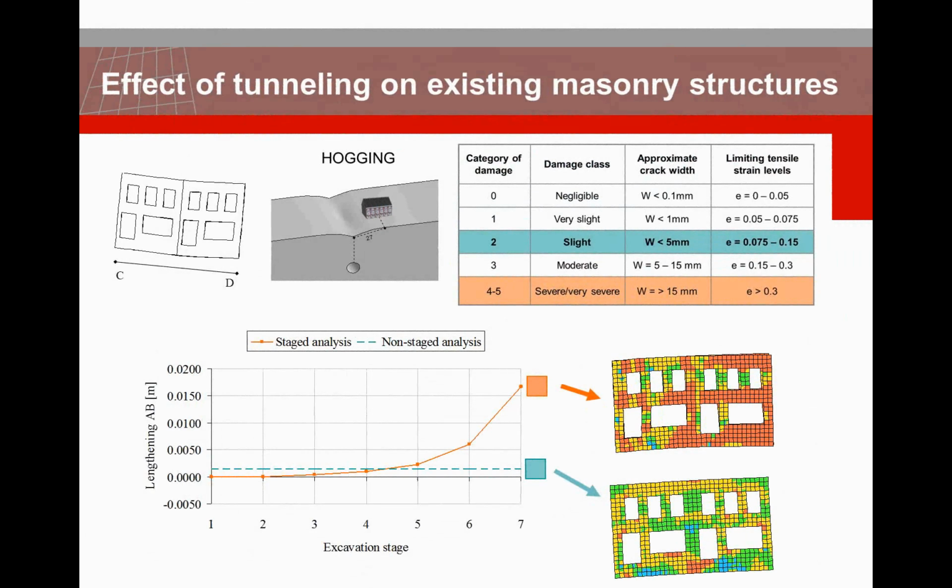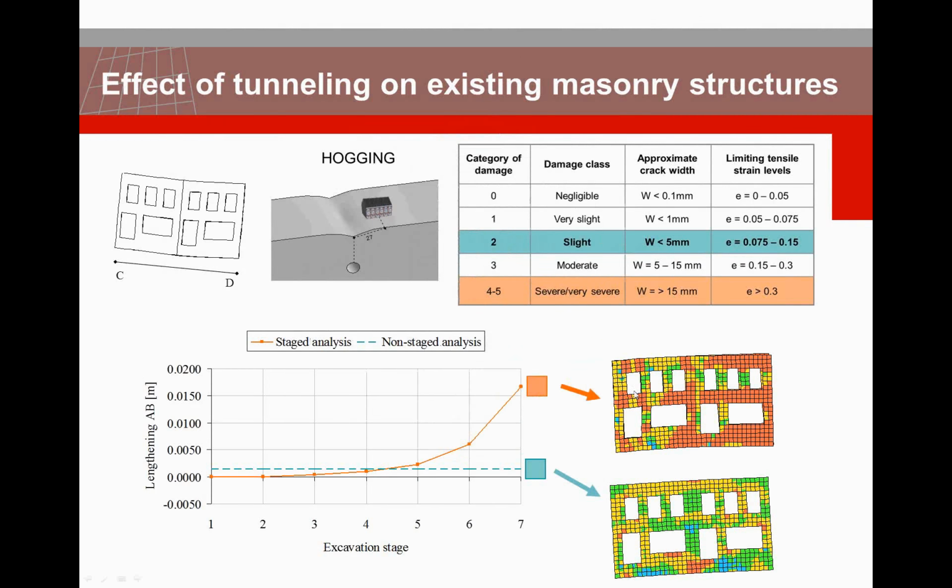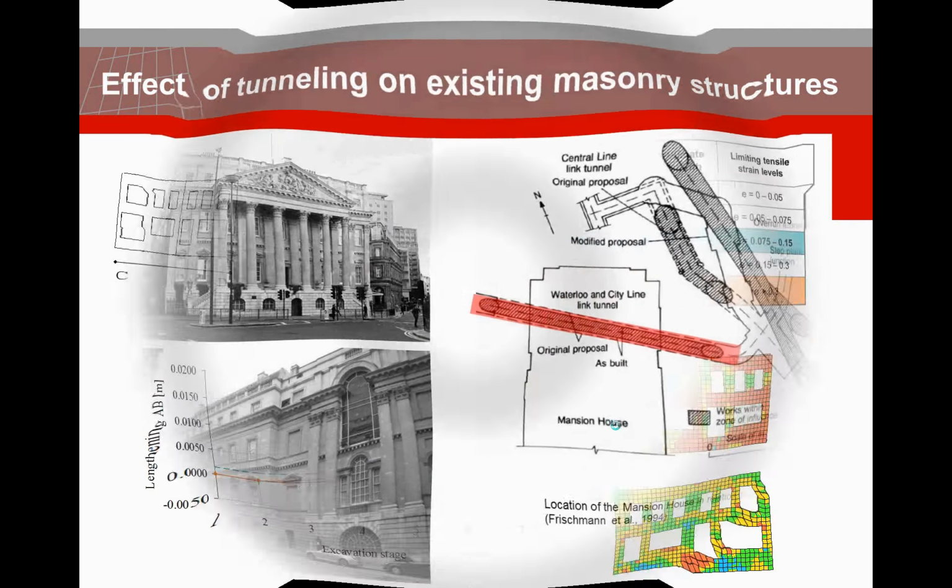So the simulation here is conducted in a way that either you consider the whole excavation process in one go, or based on the segmental excavation and reinforcing the inner tunnel, and how you can control that effect on the superstructure. So here you can see the induced cracks on the top building.